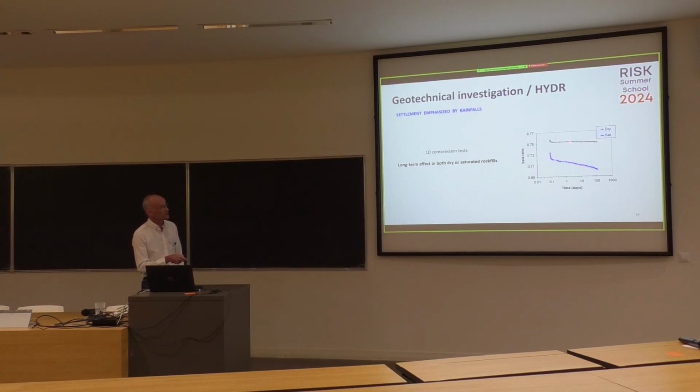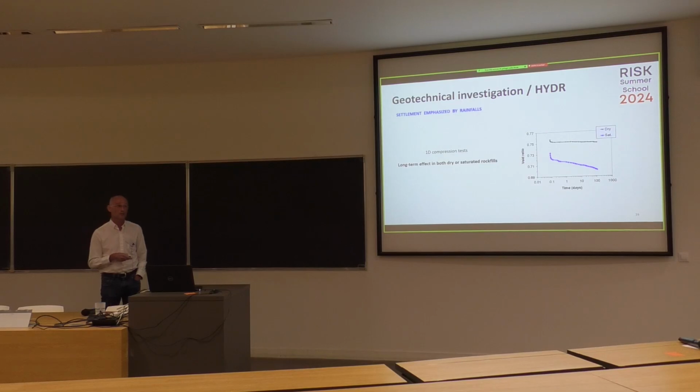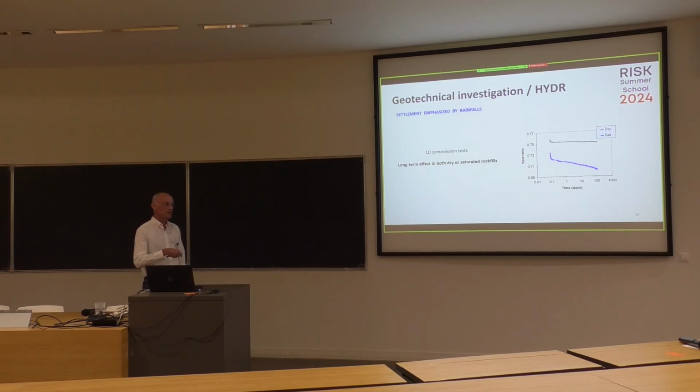You see that there is a gradual decrease in the volume. And this decrease is more important in the saturated conditions. So what we observed in the lab corresponds exactly to what was monitored in the field. So the problem is this long-term effect due to the water, to the interaction between the water and the rockfill.